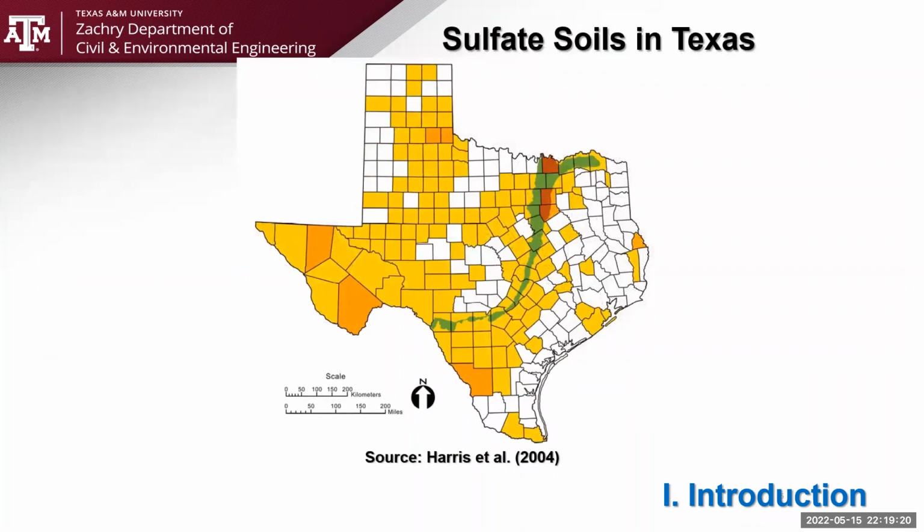In Texas, where we have done a lot of work, there are many locations identified where there are sulfates. So this will tell us that when we are building low volume roads to moderate or high volume roads, we will know what stabilization one should focus on. You can't just go with the same type of treatment, because that will cause these man-made sulfate heaving problems. So we want to be very careful in screening the soils before we select the appropriate stabilization.